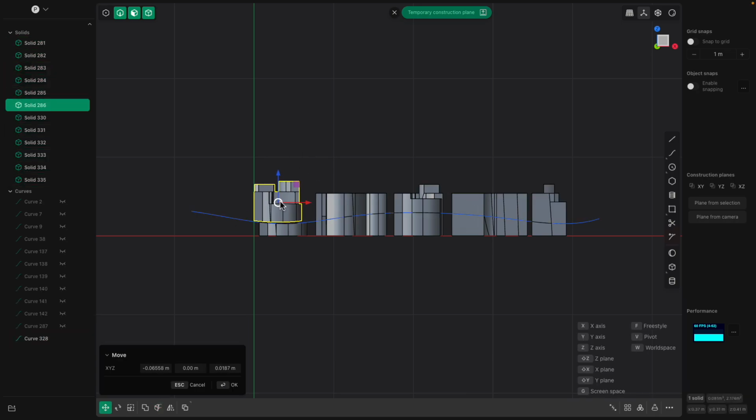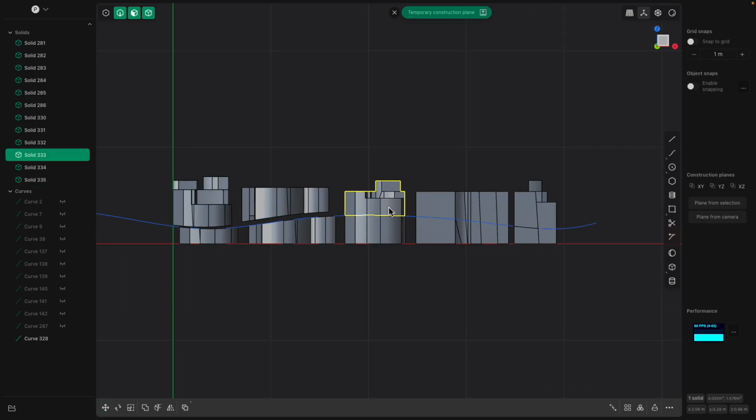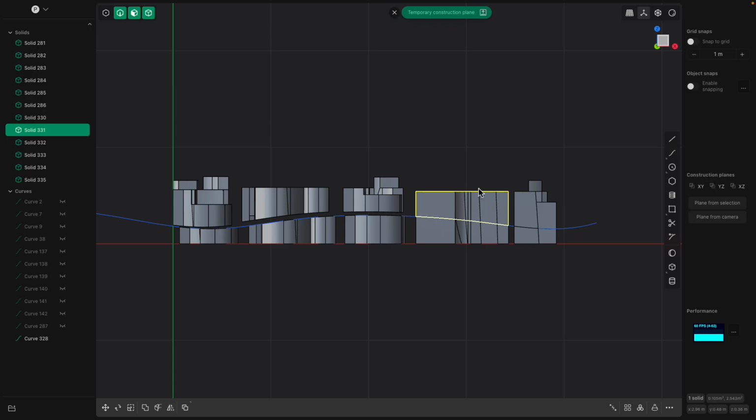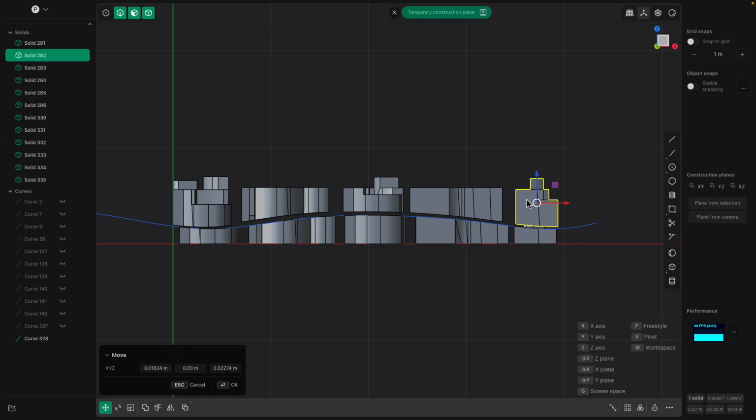This will actually work. I wish in Plasticity there was a quick way to simply grab. So at the moment I need to select and then G and then move. Oh, okay, select and G does the job.